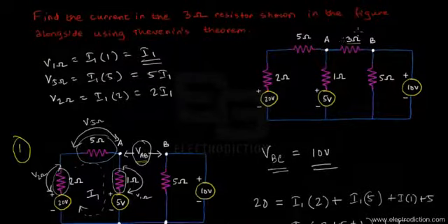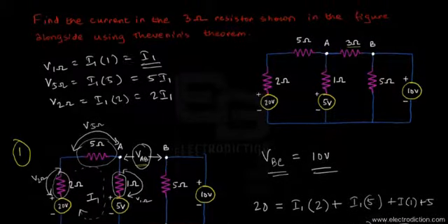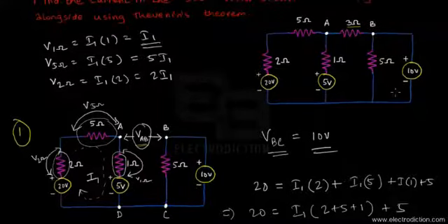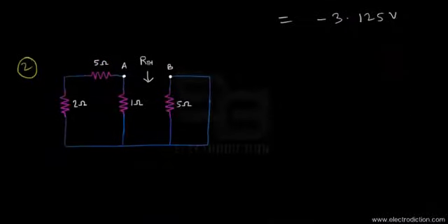If you compare this diagram with the original one, you can see that this was the original circuit, and now we have shorted all the voltage sources. Since there are no current sources in the network concerned, we need not think about them. So here is the network which we are going to obtain. But wait a moment. On the left part of this network, we can just go forward and obtain the net resistance.